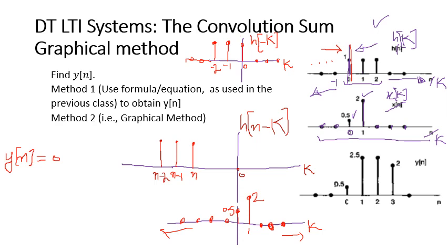So this is how you get zeros, because one of the signals is 0, then you take the next value of n. Basically you are moving the signal, in this case, towards the right. Then you shift this signal right, and again you take the products, because step number 6 says that we do it for all values of n. So now we are changing the value of n.